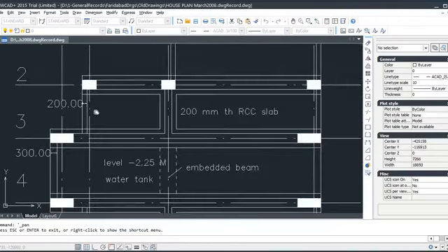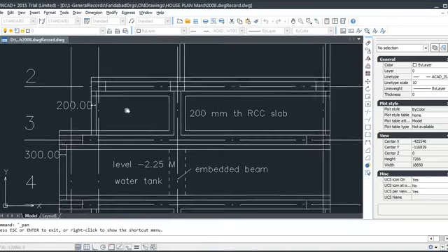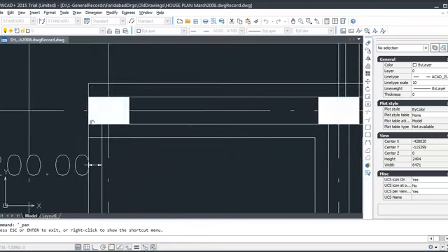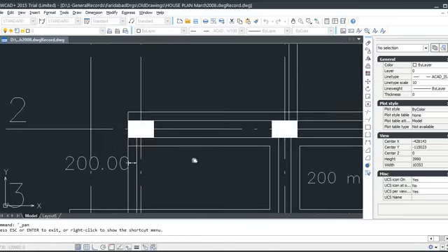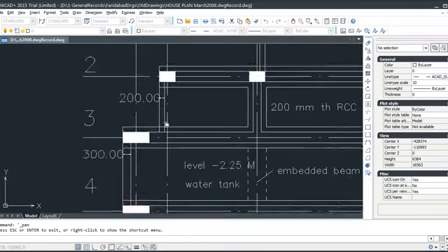Comfortably, we have to keep in mind that fire is to be taken into consideration. In case of fire break, first of all, I provided fire tank or common fire and portable water tank. That's one part. But there's another part. Suppose your building gets fire, what solution is there? At least 1/4 of this column, or 1/4 to 1/3 of this column, external surfaces shall catch fire first. This is very common. Not only this column, also these beams, 3 sides shall get fire, 2 vertical and 1 soffit. This would be subject to fire.